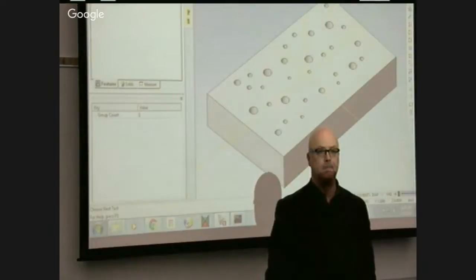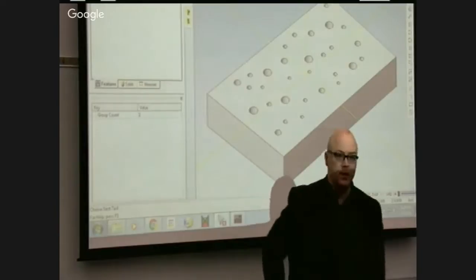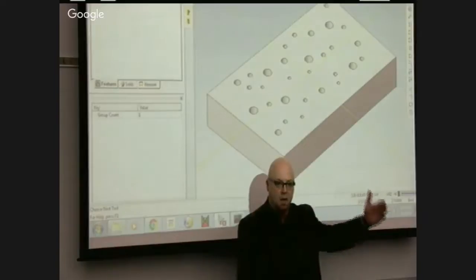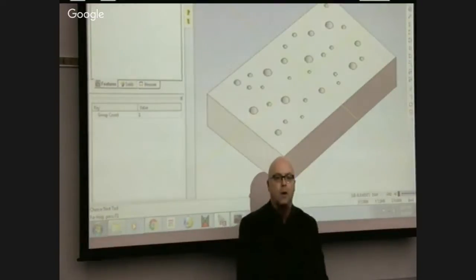I would say drilling all of one of the same size holes. Okay. So then you're going to have, so how did we create our tools again? First we had to figure out what the dimensions of the holes were, right? Then we selected tools. Now we're going to have to create operations, and the operation is going to have to select the correct tool to do that operation. Right? What's the next step?